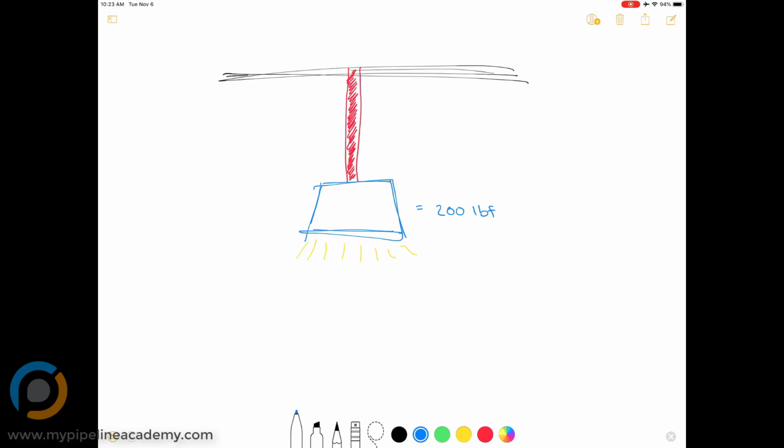Unless we're taking into account, this is going outside the scope of our problem, but if there are little vibrations that change things a little bit, then it could be months, maybe. But if it's just a static thing hanging there, it's probably either going to fail pretty quickly or not at all. Okay. So, yeah, that's the point. Yield strength, yield point. Okay. We don't want to exceed that. Right. Okay, so one thing we need to understand is what is the stress in the aluminum rod?